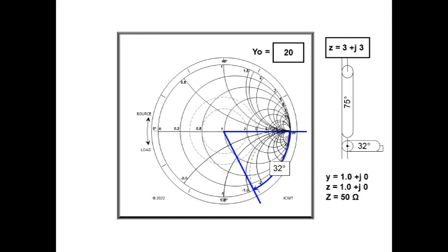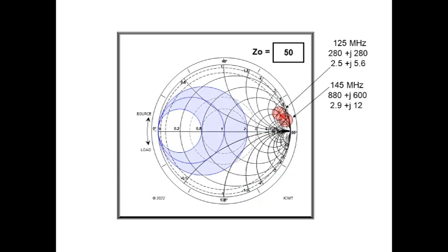We challenge you to find an antenna impedance that cannot be brought to 1:1 SWR this way. The answer is, none. Though everyone shoots for that holy grail of 1:1 SWR, good engineering sets a maximum value to be tolerated. Here we show the target circle as a shaded region. With the proper length of coax, an impedance can be brought into the shaded area.